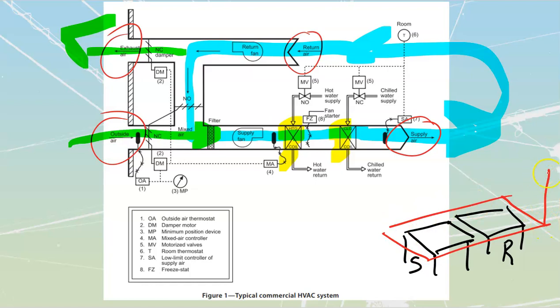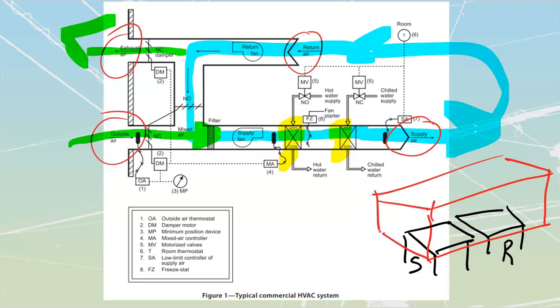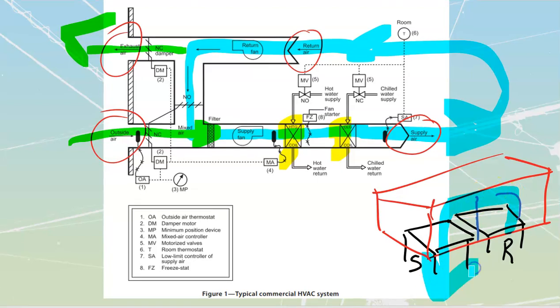And when the rooftop unit is on top, let me just actually redraw that just a little bit better. When we get that all the way onto there, what happens is that my rooftop unit is going to contain all of these components. So it's going to take the air in, it's going to be segmented, it's going to take the air in via fan, and then that air will travel from here, it'll travel through some coils that are either going to heat it or cool it, and then it's going to travel back down into the building like that. Once again, a little bit of makeup air is also going to happen inside of these, meaning we're going to expel a little bit out, and then we're also going to take a little bit of fresh back into our units.